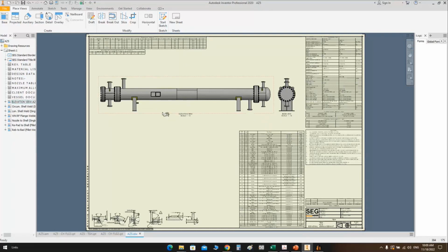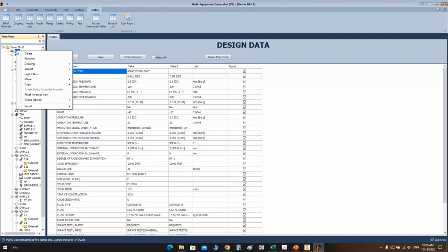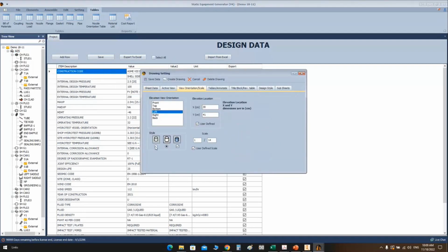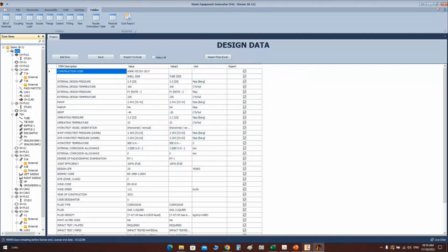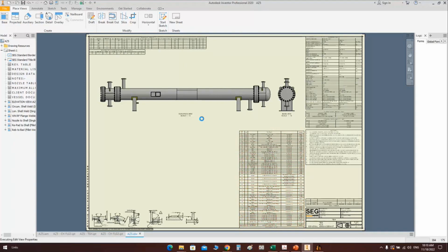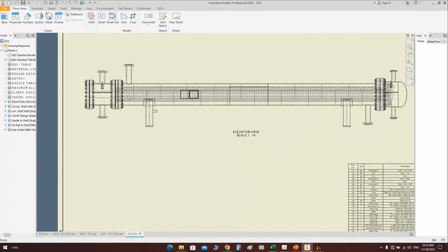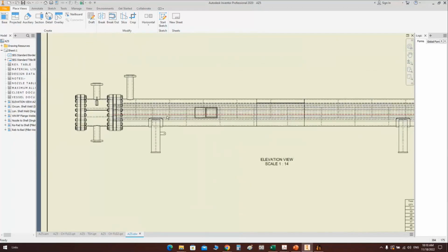Okay, now if you would like to make this view without color and make it with hidden lines, how can we do that? As we discussed, from this view, if you would like to generate a drawing from here, you can make this view without color. So we will remove the shaded type and make it with hidden lines. Let's select hidden lines from here and click on create drawing. By that way, we can modify the style of lines, and make the hidden lines visible like that.